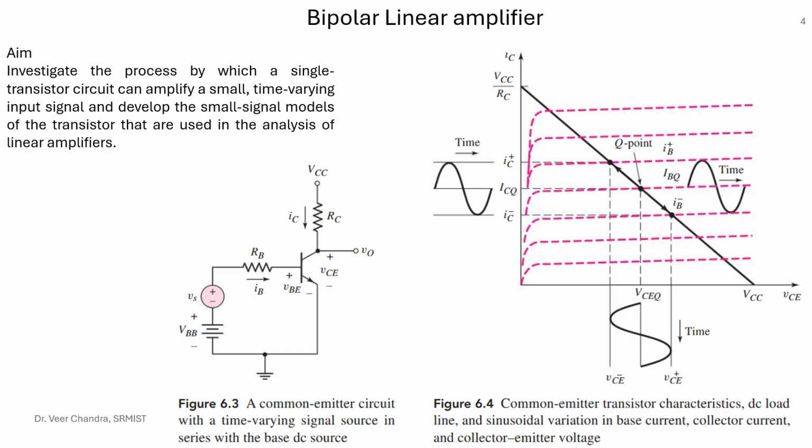In order to design your transistor based amplifier, the BJT itself is not enough. So how will we do that exactly? You must connect your collector terminal with some resistance, your base terminal with some resistance, and some resistance with the emitter terminal. Then you give the input signal that you want to amplify at the base terminal, and collect the amplified output at the collector terminal. This is how to design your BJT based amplifier.